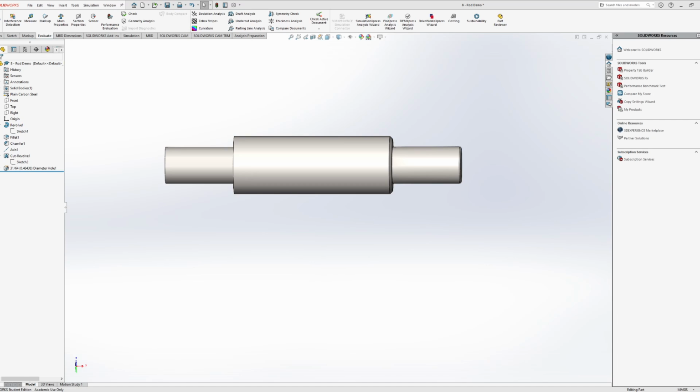If I'm doing a cantilever, with a fixed end and a force on the very end of that cantilever, then even if I'm using the exact same measurements for everything, if I rerun that simulation twice, or delete the results and rerun it, I might get slightly different results. It might be a difference of 3.01 and 3.02, but it's not always exact. So sometimes there is a little bit of leeway. Sometimes the results are even more different than that.